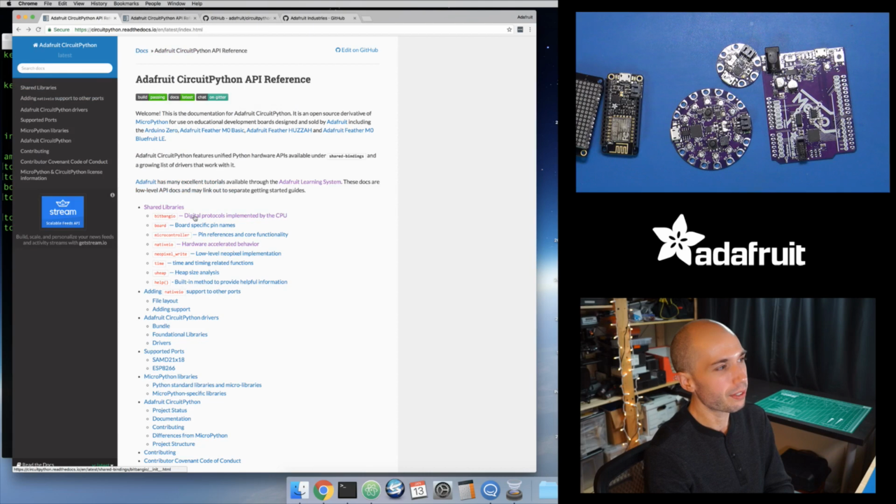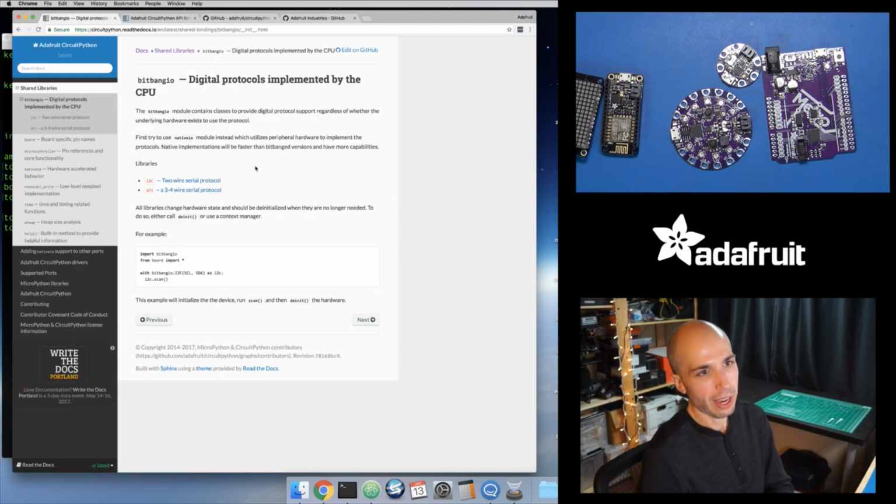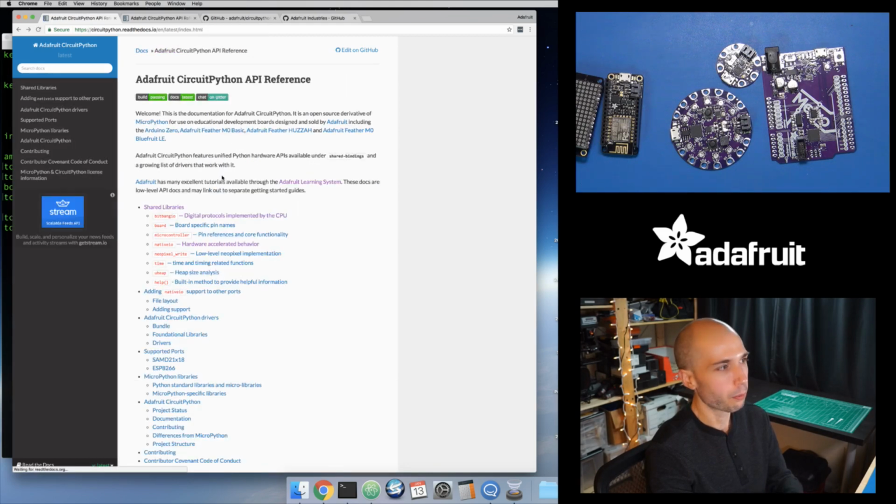Now, the interesting thing is there's a version called bitbang I/O. This actually has a bitbang, or software, implementation of the I2C and SPI protocols, and it has the exact same interface as native I/O. So the nice thing is you can swap between them if you need to use maybe a software SPI to talk to a little TFT LCD that you hooked up to some digital input lines. Without changing all the driver code or all of your example code, you just change which module you import, and your code will be pretty much the same, but you're using a software or bitbanged interface to that device. So hopefully it'll be really easy to swap between those by keeping the interfaces the same. That's what the bitbang I/O module is for.